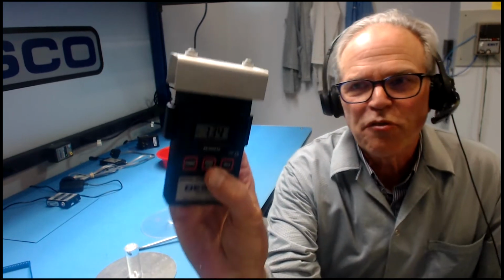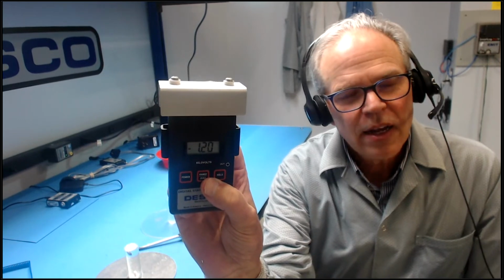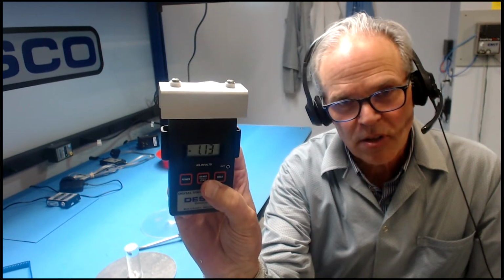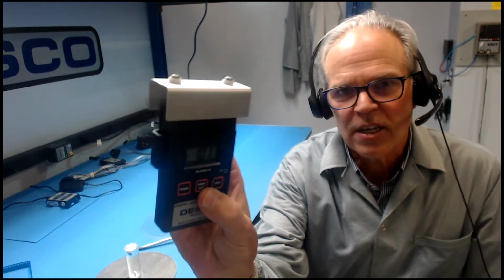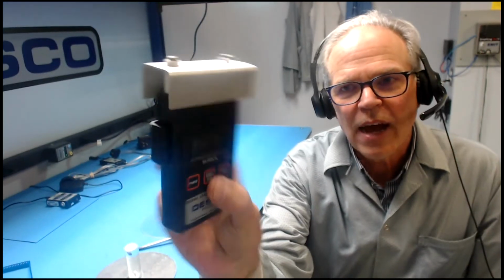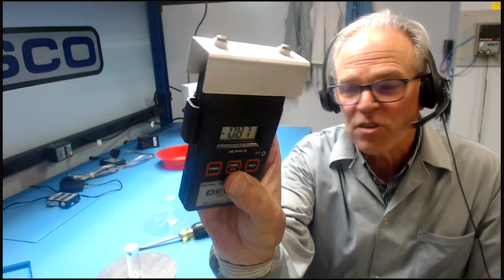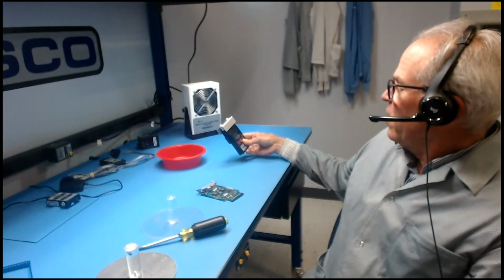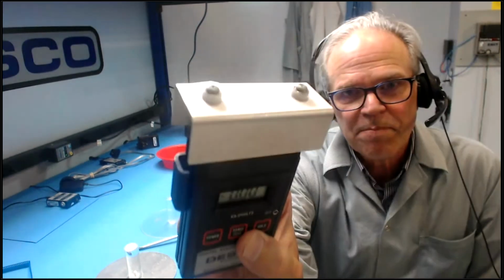So that's 1,400. When you have it on the ionizer, you start counting down when it gets to 1,000, and when it gets to 100, you stop counting, and that's actually your time. So you can see it's very slow because it's not in the air ionizer. So I'm going to put it over here under the air ionizer, and you can see the charge is gone.